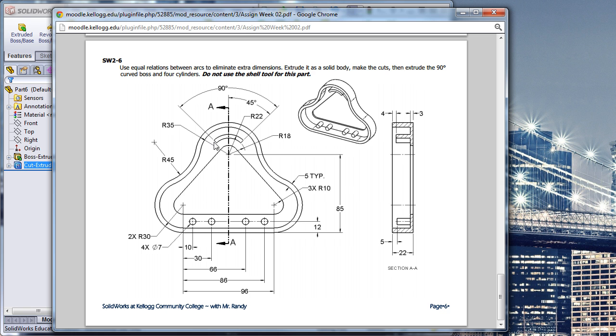And then finally, this shape right here is 2 arcs at an 18 and 22 millimeter radius from the same center point. And there are 2 lines here. And you'll notice that it's extruded up, offset from surface 4 millimeters. I want you to be very careful. When you draw this line in, and you draw this line in, SolidWorks will probably give you a witness line when you do the second line.